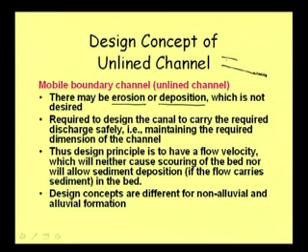Suppose the water was flowing with a particular velocity. Now, when deposition is taking place, the flow velocity gets retarded upstream, because it is getting some obstruction. If it is a subcritical flow, it is retarded. When it is retarded, its sediment carrying capacity further drops down and then further deposition takes place. That way, ultimately the entire channel slope gets reduced.